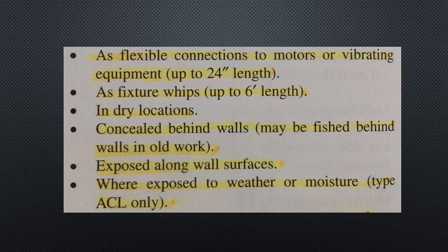Armored cable, AC and ACL. Type AC or ACL, often called BX cable, is used in both dry and wet locations, but is not permitted to be buried. See figure 5-8. This type of cable, once commonly used in many applications, has some limitations for commercial use. It may not be used in places of assembly, studios, movie theaters, hazardous locations, commercial garages, areas with vapors and corrosive agents, lifts, cranes, hoists, elevators, or battery rooms.